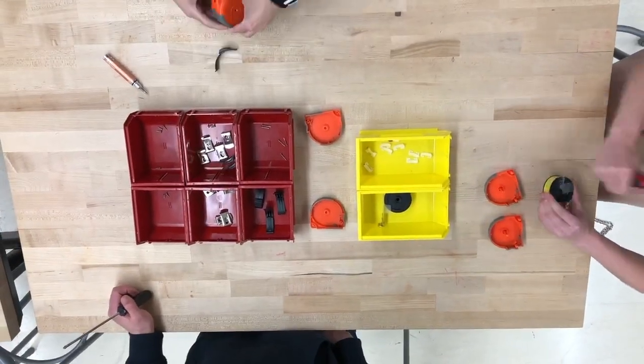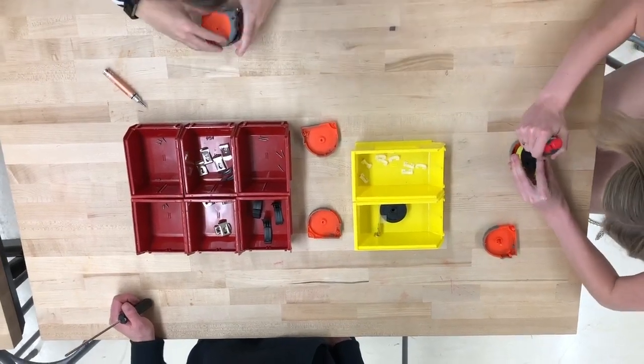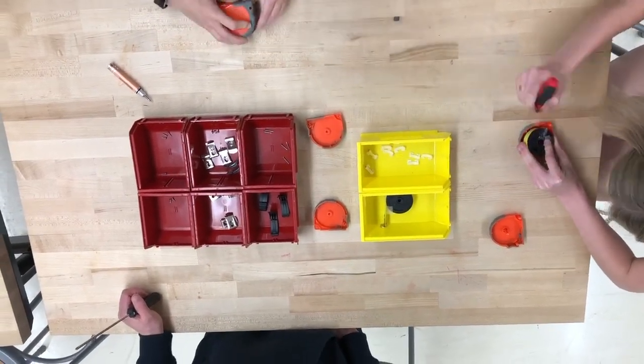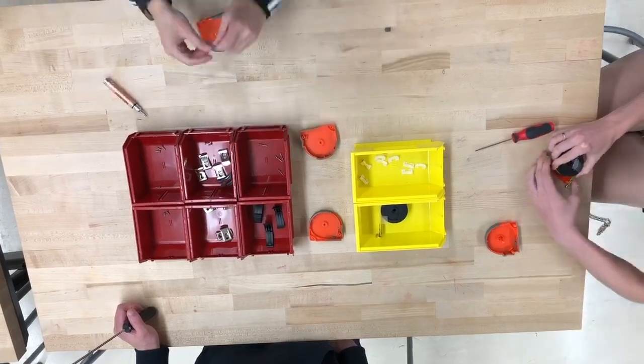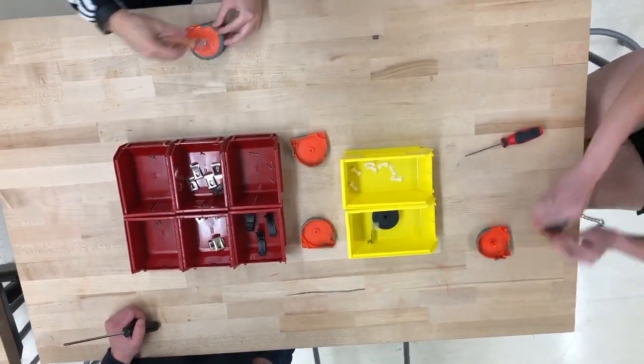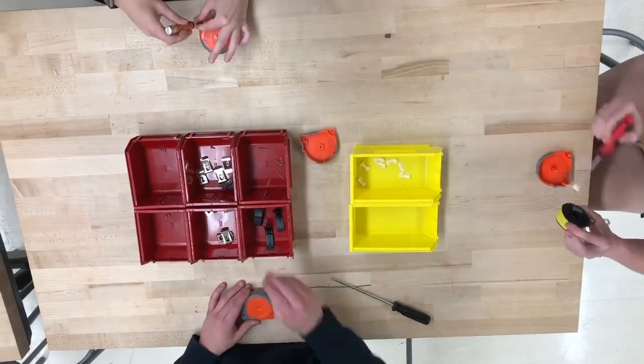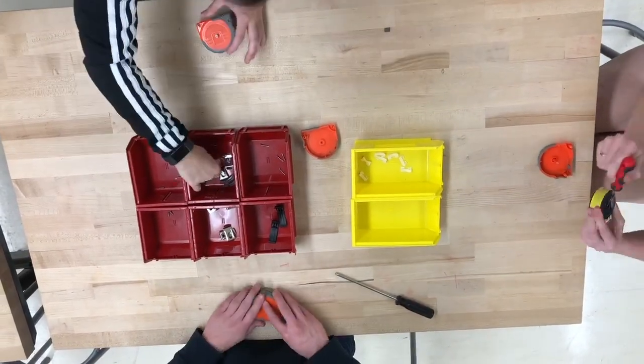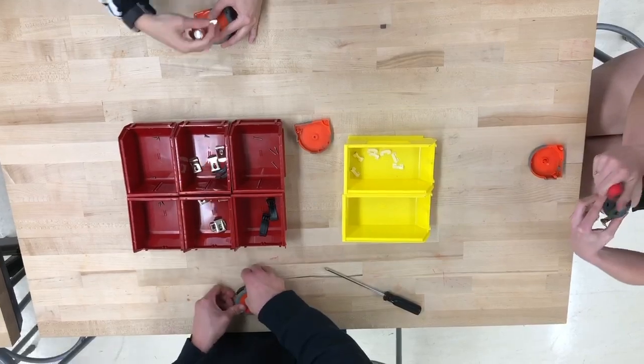For example, at Workstation 1, where it was required for the operator to align the spring with the case peg, it was often found that this process created a bottleneck. This was because it was hard to obtain the spring, and it was also hard to align it into the slit of the case peg.